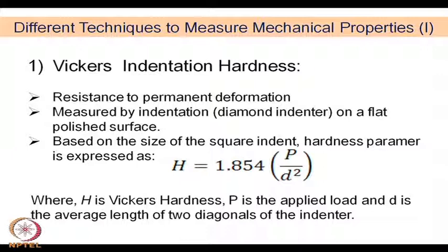So, whatever small it is, obviously compared to ductile material, for brittle material or for ceramics in particular, the permanent deformation is negligible, and therefore, you need a larger amount of stress or larger load to make an indent, but some amount of indent can certainly be done. Since ceramic materials are very hard, we always use diamond, and that is by definition, because indentation always uses a diamond indenter, and it is in the form of a square pyramid.